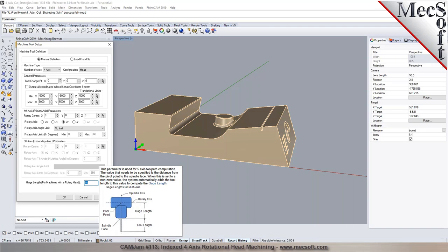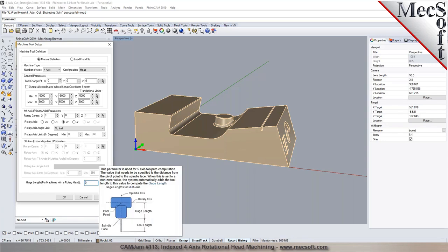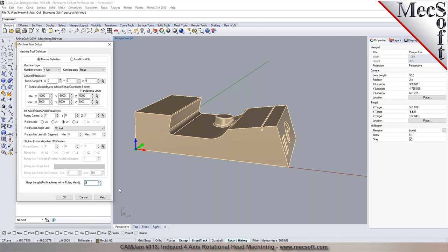Okay. So that parameter will be constant for a given head on a CNC machine tool, but what would be a variable is the tool length, depending on the size of the tool that you're going to be using and how far it's going to be sticking out from the spindle face. Okay, I understand that. So if you put this value to 0, it means that the controller does the compensation, so we don't have to compensate from the CAM product here, like an RTCP on, or certain controllers call it G43.4 or G48.1. Each controller has its own way of handling it.